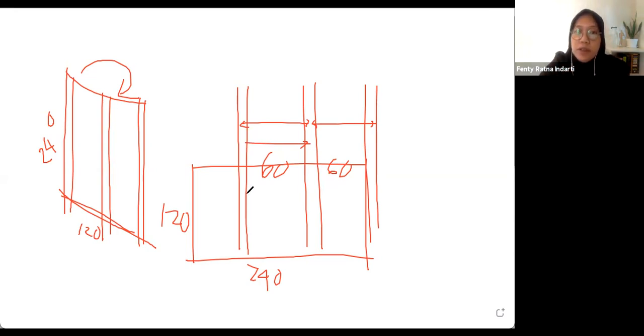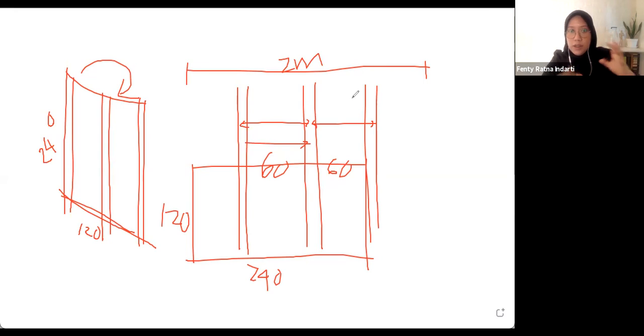And then you have to divide it, for example, like this. You have maybe 2 meters like this, and then you have to divide it into equal parts so that the lateral load, which is only the wind load, which is not big actually, is distributed evenly. So if you have 2 meters and this is about 250 centimeters, you have to cut it down.